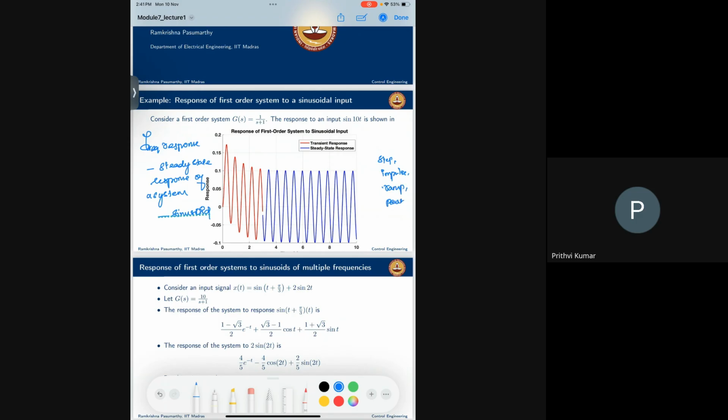In frequency domain, if someone asks what frequency response is, we'll say it's the steady state response after some time, when the system reaches steady state, when the input applied is a sinusoidal signal. So if you feed your system a sine wave, wait until it comes to a steady state point and observe the system's output, that gives you a frequency response in a real time application.